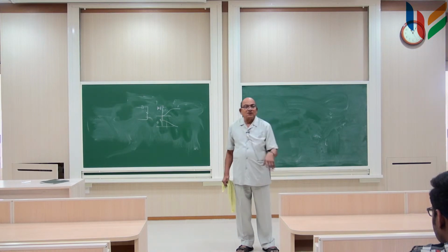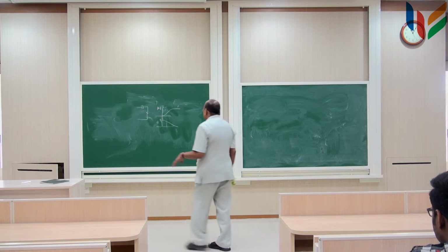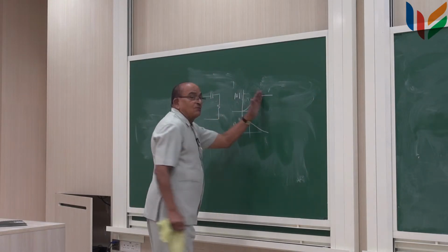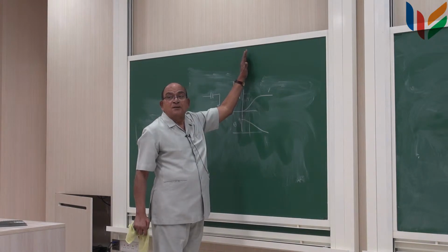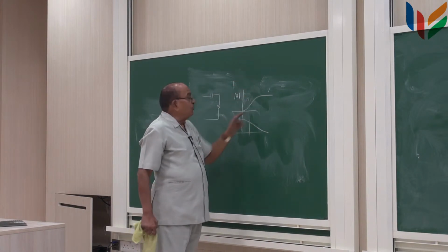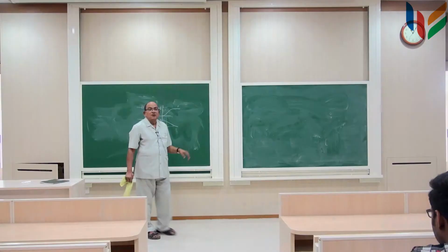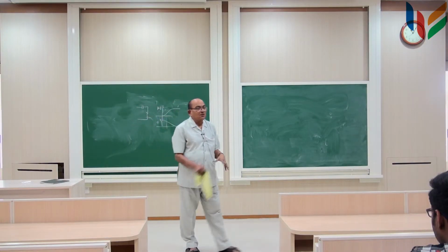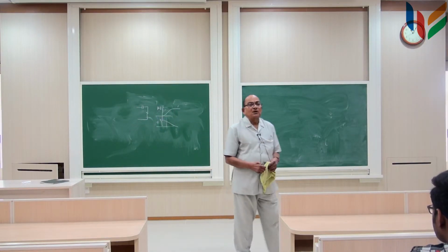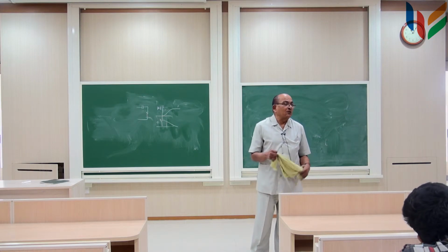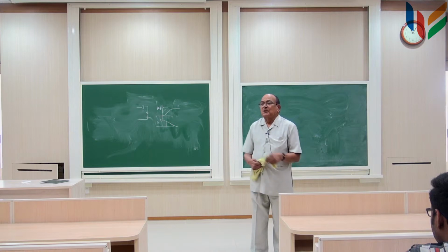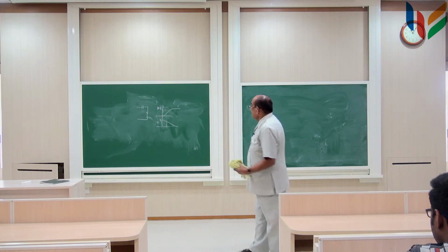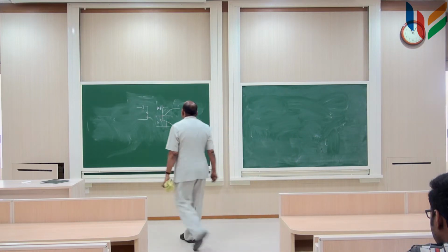So, the total angle of 360 degrees is obtained: 180 degrees from the three cascaded sections, and the amplifier provides 180 degrees by a minus in the amplifier A. So, overall phase shift is equal to 360 degrees. So, this was the viewpoint on which the phase shift oscillator was designed, using this concept of phase shift. That is why the name phase shift.